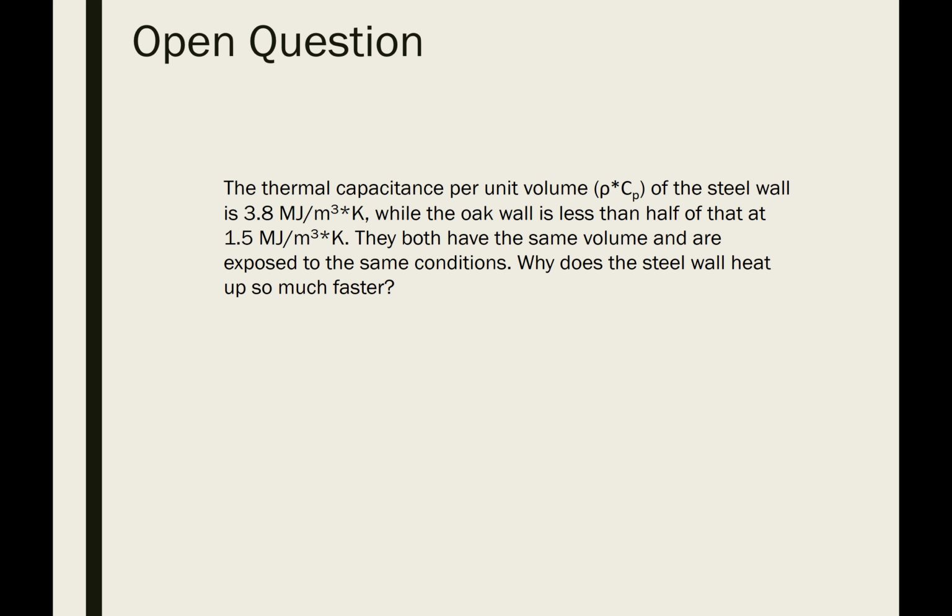Anyone want to say it out loud? Okay, yeah, the rate at which heat propagates through is so much faster. While you couldn't use the thermal resistances in series method explicitly to solve for this because it's not steady state, that idea still qualitatively applies: the thermal resistance through this steel is a lot lower because it has a much higher thermal conductivity.